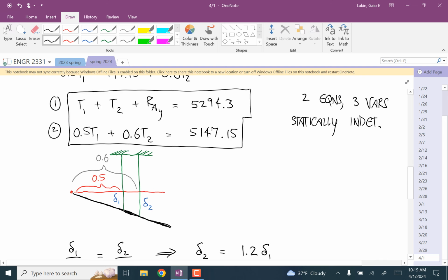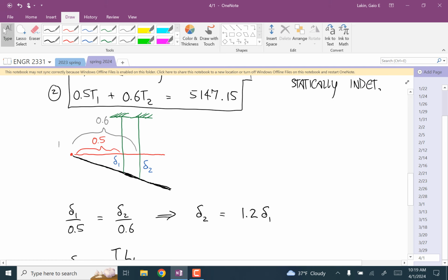Notice that just from the geometry, you can see that as this thing tilts down, the farther away you get from that hinge, the more stretch the cable is going to have. If they're different materials, it's more complicated figuring out what the forces are. But you're always going to have more elongation as you get farther away from the hinge.